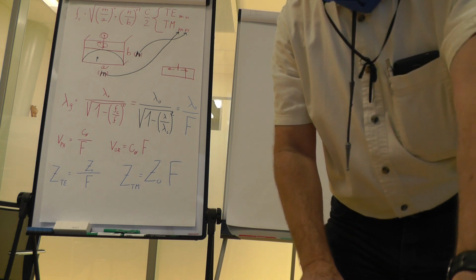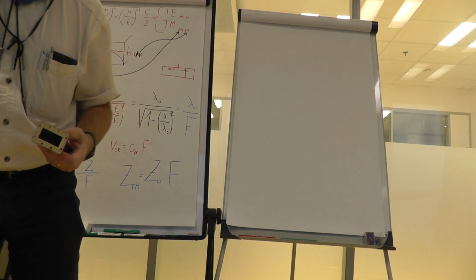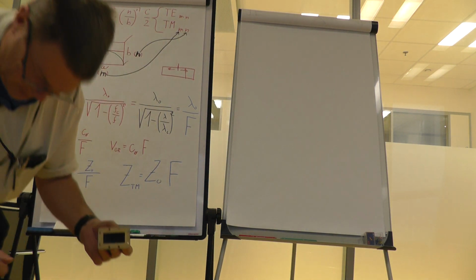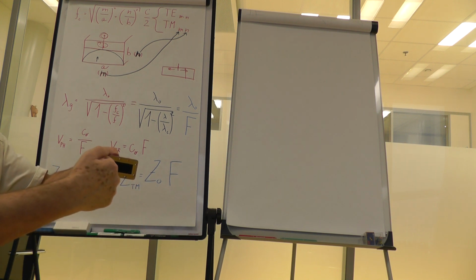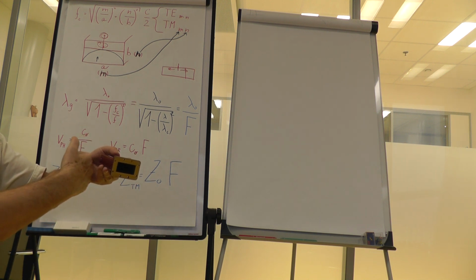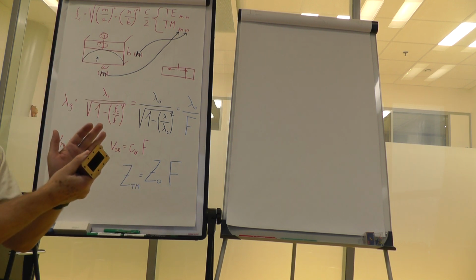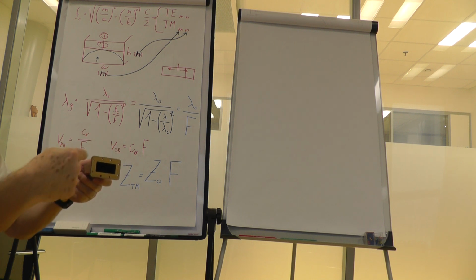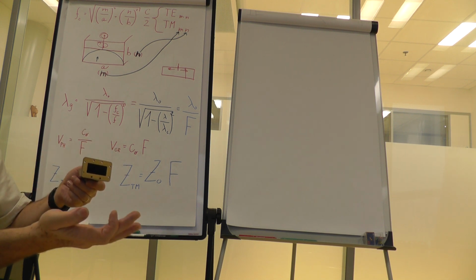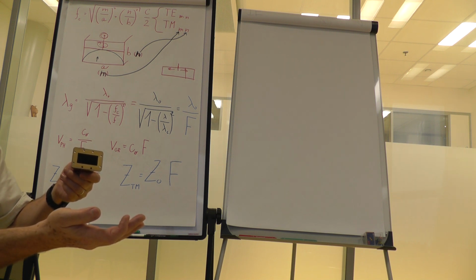Well, after talking about this, we sometimes need also a device that is called a matched load. We need the wave in the waveguide to be absorbed and not reflected back. If you just put a metallic closure on a waveguide, you would not achieve that. The wave would reflect back in full magnitude and cause interference and standing waves on the line.